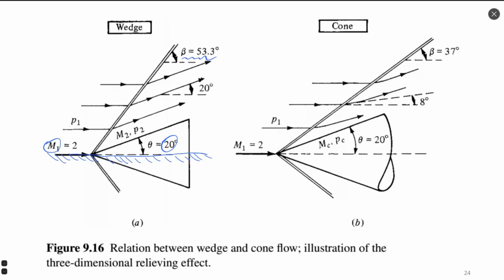And then provide all calculations as I just showed you in the previous example. When we see the second case, flow over a cone, a cone is a three-dimensional structure, a rotational body. In this case, flow is different. First, flow lines or path lines after the shock wave are curved because the area of the flow is changing significantly